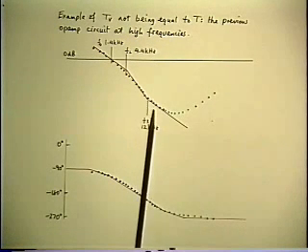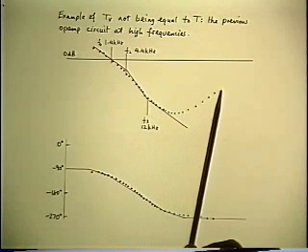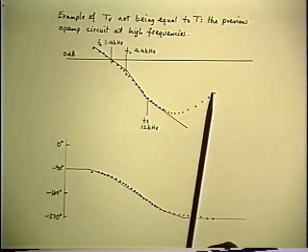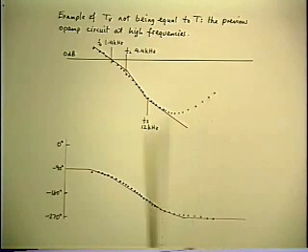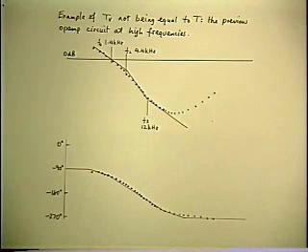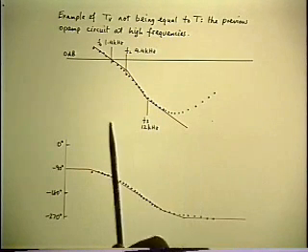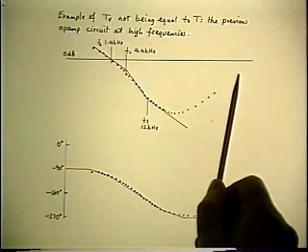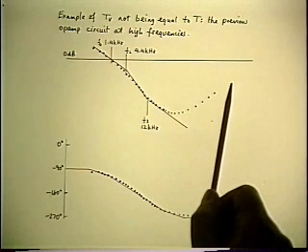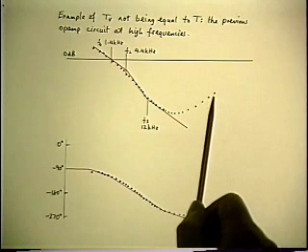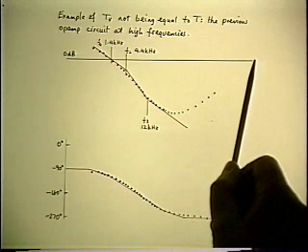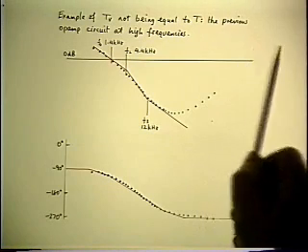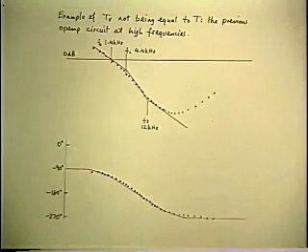The loop gain turns around and goes back up. Now, that's a little distressing, because if you've designed a feedback amplifier whose loop gain turns around and comes back up at higher frequencies, who's to say whether it may come actually back above 0 dB again, which means you'd have to satisfy Nyquist all over again, maybe up in the megahertz region.